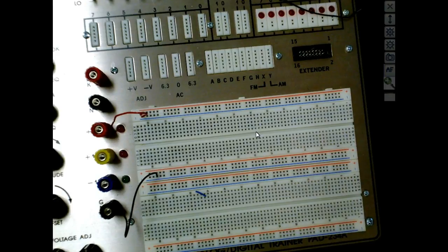When we take the information off the carrier and strip it off the carrier, we call that demodulation. So what's a modem? It's a modulator demodulator, right? And that's what it's doing. It's taking your information and placing it on a carrier at a higher frequency, and then when it gets where it needs to go, it has to go through the demodulator to strip the carrier off, which is basically